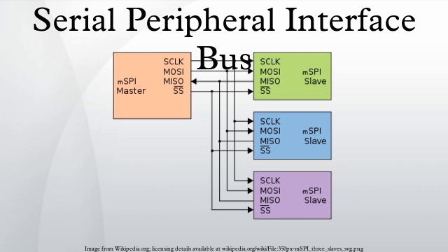All communications that were out of band of the LPC bus, like general purpose input-output and system management bus, are tunneled through the ESPI bus via virtual wire cycles and out-of-band message cycles respectively, in order to remove those pins from motherboard designs using ESPI. This proposed standard will support standard memory cycles with lengths of 1 byte to 4 KB of data, short memory cycles with lengths of 1, 2, or 4 bytes that have much less overhead compared to standard memory cycles, and I/O cycles with lengths of 1, 2, or 4 bytes of data, which are low overhead as well.